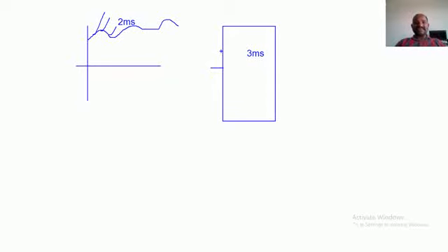In order to avoid this kind of problem, we have one device called a sample and hold circuit. We usually call this S/H, sample and hold circuit. Whenever there is a mismatch between the two components, the sample and hold circuit samples the input signal with the same time period and holds it. The sampled information will be stored by the sample and hold circuit for some period of time.